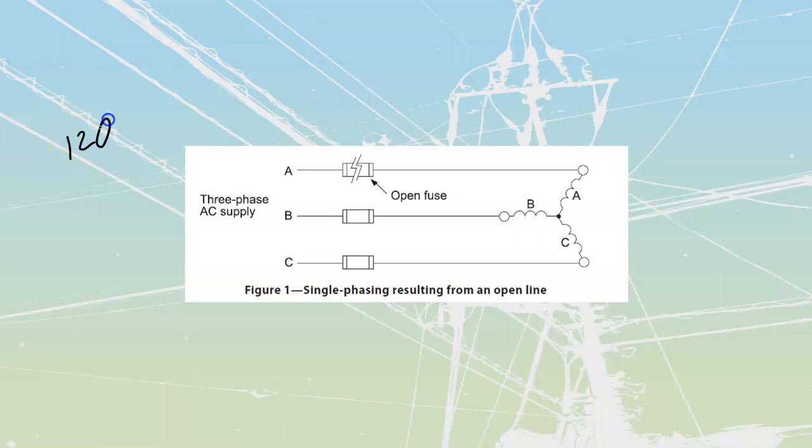First of all, we have a 120/208 volt type of system, which means that we have a line value and a phase value of voltage, and therefore over top of each of these, 120 volts over top of my individual loads is what I would normally be seeing over here. Line to line, I would have 208 volts.